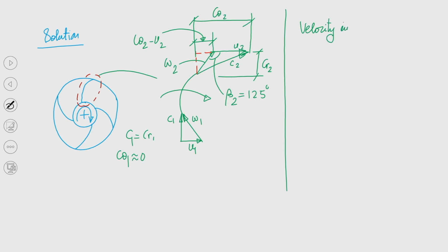So, the first step is to calculate the velocity in both pipes. I am writing V with suffix S, D, that is suction, delivery, which is nothing but 45 liters into 10 power minus 3 meter cube per second. This unit conversion factor is there, divided by pi by 4 into 150 mm.